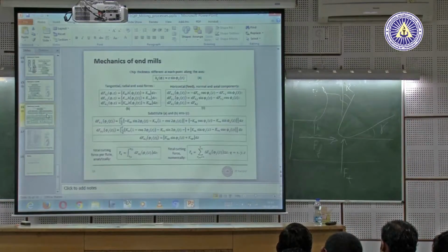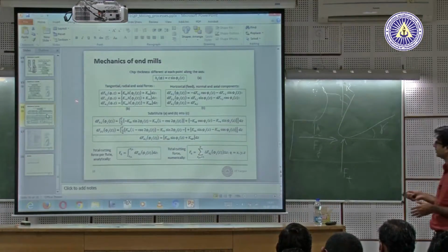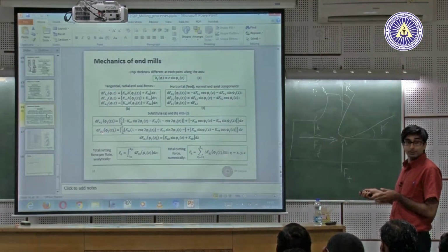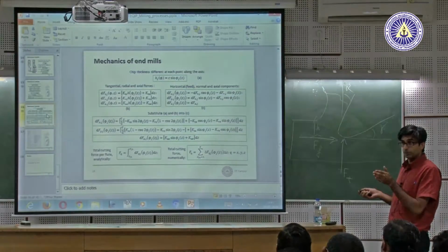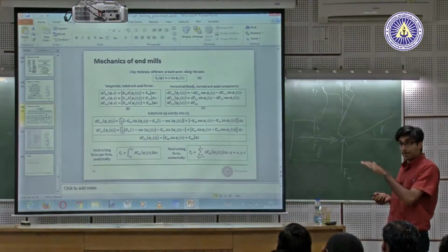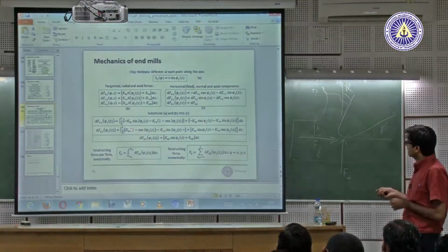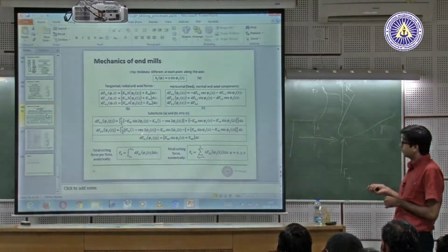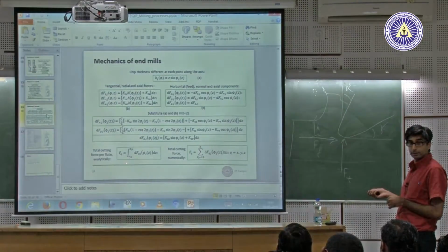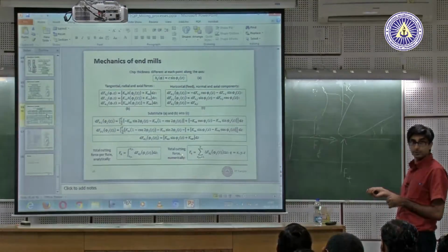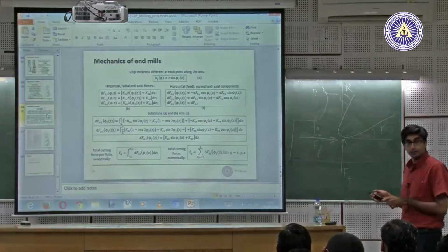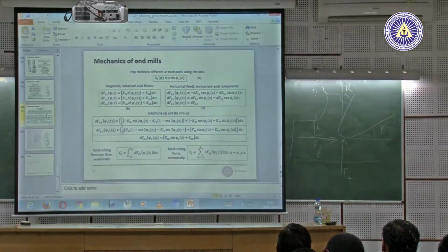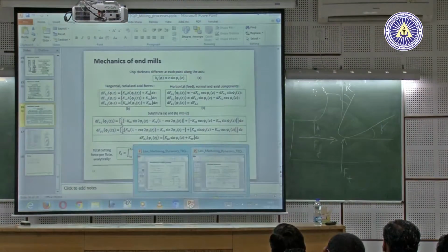Okay. So if you remember this, yesterday we were looking at discrete elements. We were looking at how h changes as a function of phi and as a function of z. So this is at the elemental level. You can sum forces over all teeth and calculate analytically. We did not discuss this formulation; we discussed only a numerical simulation yesterday. But if you pursue this a little further, you get a nice big closed form analytical solution, which we simplify to get this.